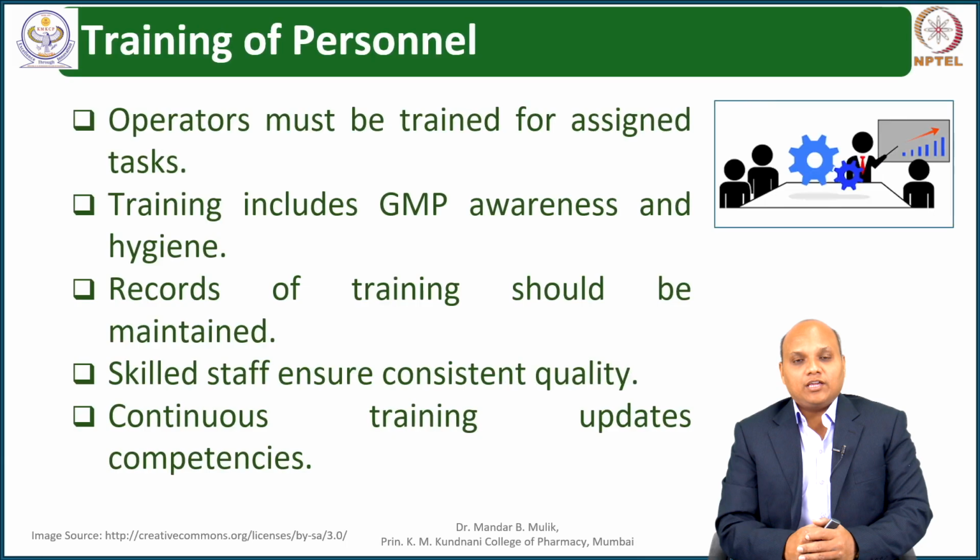To get discipline in the workers and operators, regular training is important. Operators must be trained for their assigned task. If a particular operator's task is to operate the tableting machine, then how that machine works, what is the principle behind it, which are the critical points for tableting, and which parameters need to be evaluated during the in-process stage, all that training needs to be given to the operator, so that it will not get skipped from the quality angle.